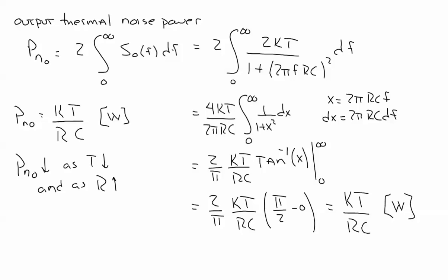Always keep that in mind. When you're dealing with thermal noise, cool circuits and large real parts of my equivalent impedance are to my benefit. Okay.